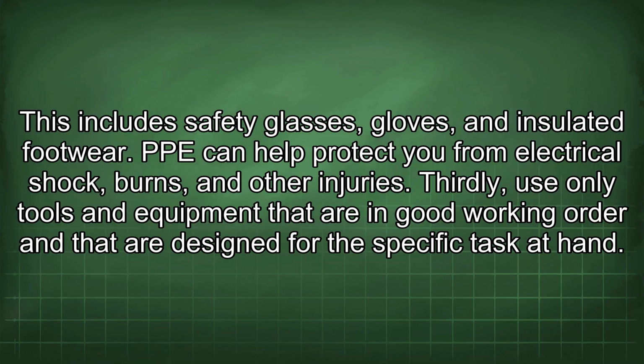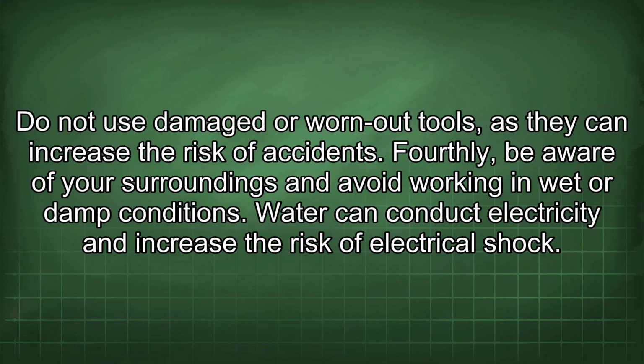Thirdly, use only tools and equipment that are in good working order and that are designed for the specific task at hand. Do not use damaged or worn-out tools, as they can increase the risk of accidents. Fourthly, be aware of your surroundings and avoid working in wet or damp conditions. Water can conduct electricity and increase the risk of electrical shock.